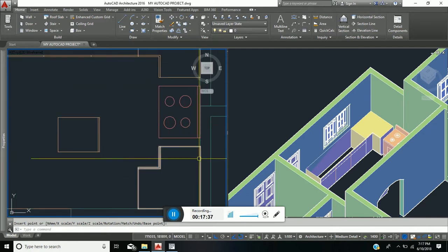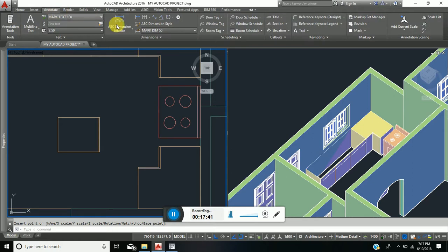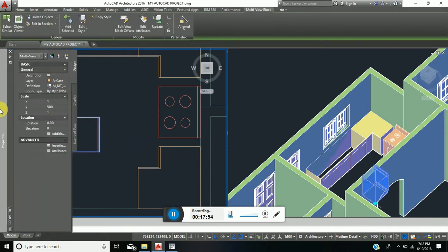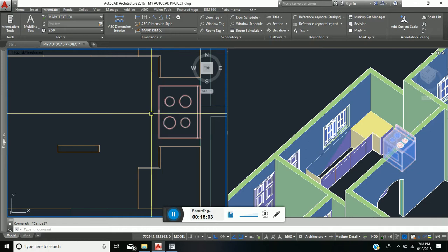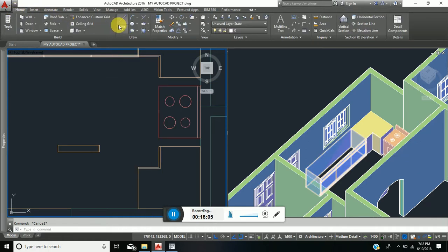Let's now find out the spacing that I need for that to fit. So let's do an annotate, and let's check the space between the cupboard and the stove. Comes out at 5 inches, 125. I'm just going to be using up 100 out of that. So I'm going to be making my cupboard 100 wide. By doing so, I would still leave space. I would have a 1-inch space between stove and cupboard.